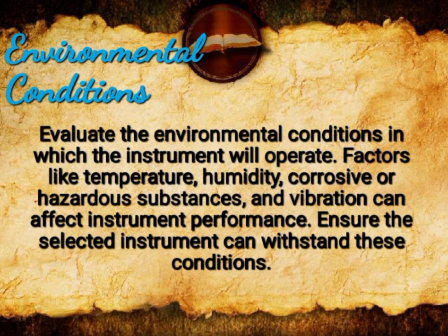The fourth one is environmental conditions. Evaluate the environmental conditions in which the instrument will operate. Factors like temperature, humidity, corrosive or hazardous substances, and vibration can affect instrument performance. Ensure the selected instrument can withstand these conditions.